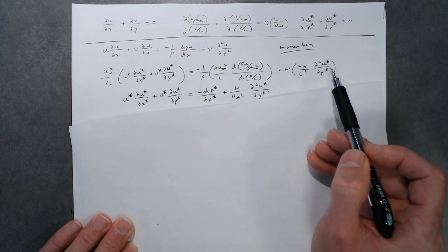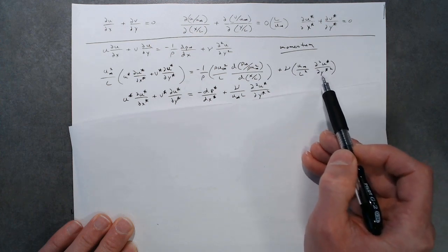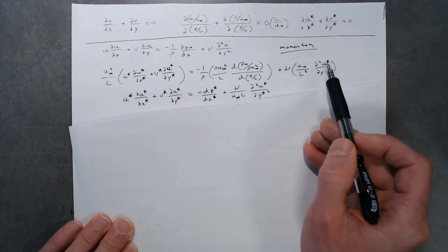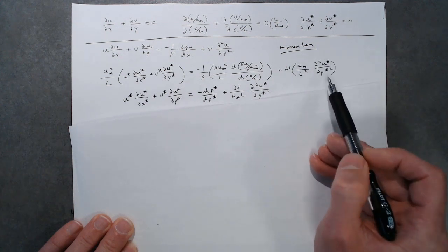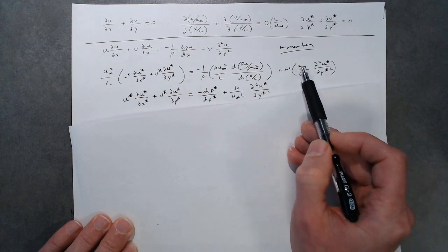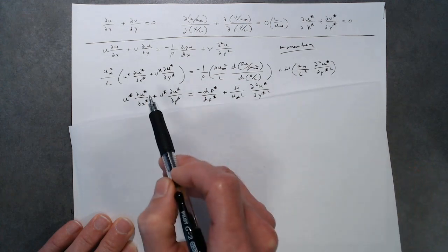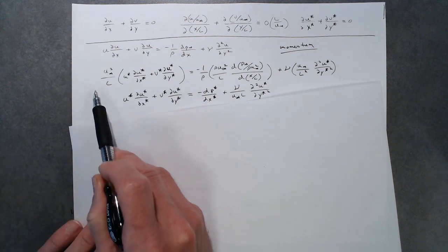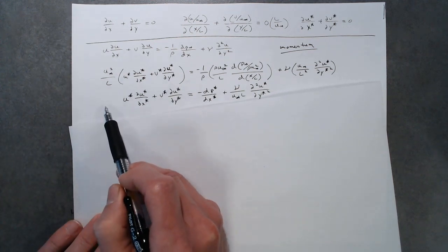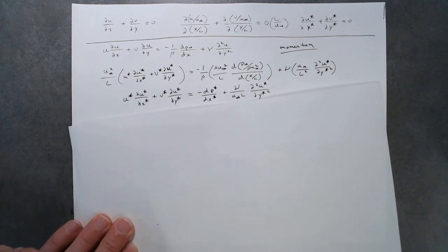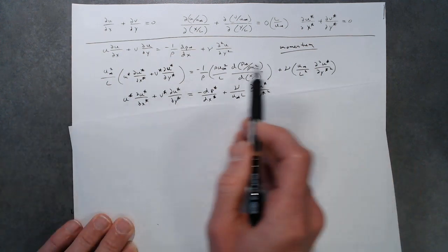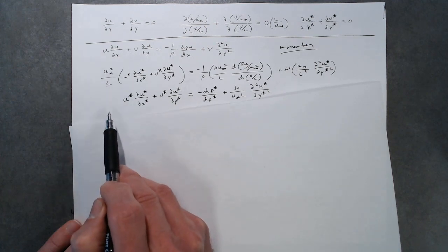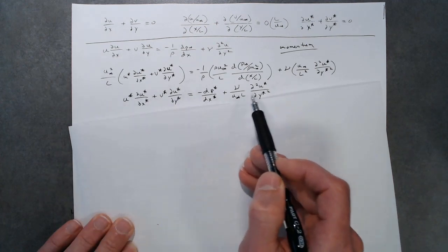And likewise, for the second derivative of u with respect to y, then we get a prefactor to our second derivative of u star with respect to y star of u infinity over L squared, analogous to what we did in this term. So if we just multiply through, or actually multiply the entire equation through by L over u squared, then we would arrive at this term.